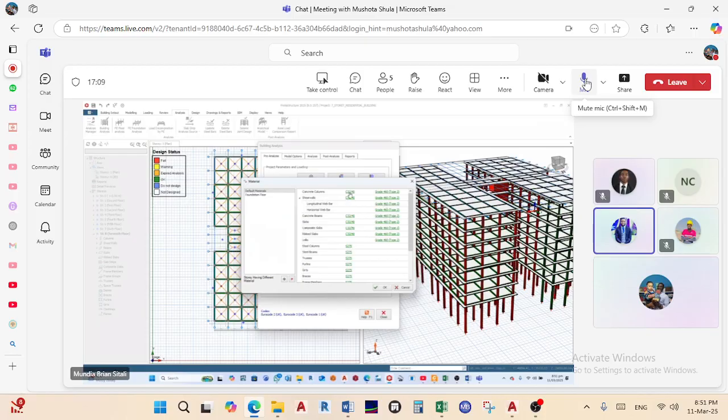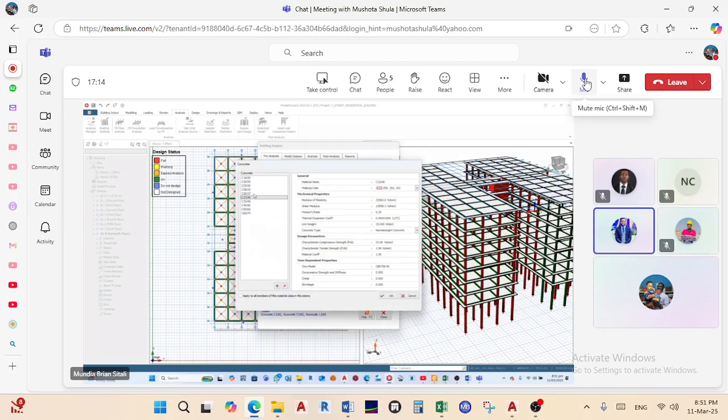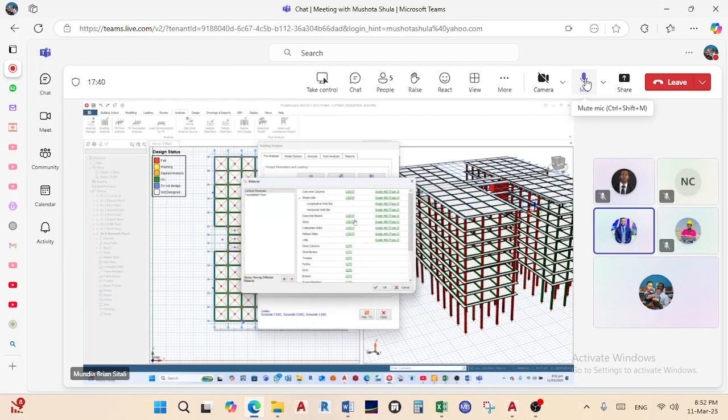Similarly, I could even say, okay, I know I want to use C40, but let me design using C30, so that when they use C40, I'm a grade higher. So that in an event that they use concrete, which gives us a strength maybe at 28 days of 28 or maybe 32, it still suffices. You understand what I mean? Yeah. So when I click that and say, okay, so everything here will be adjusted to that.